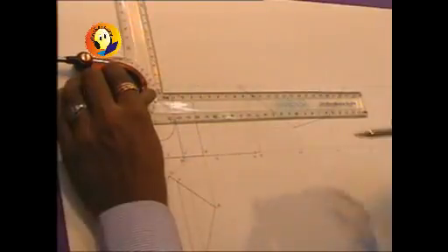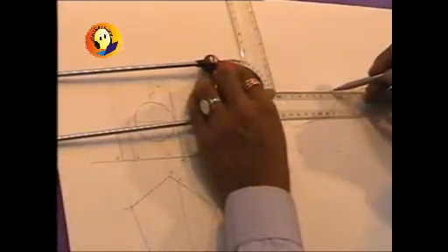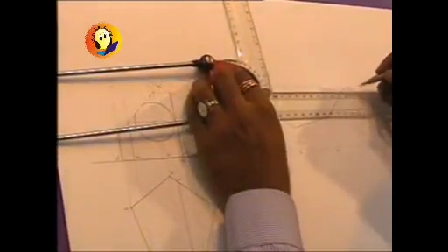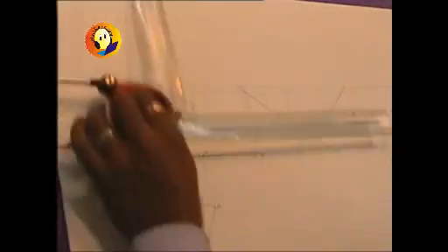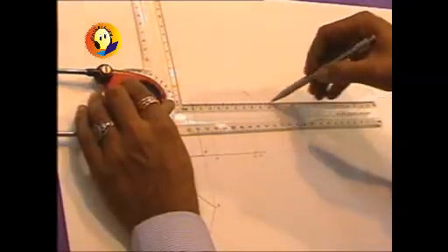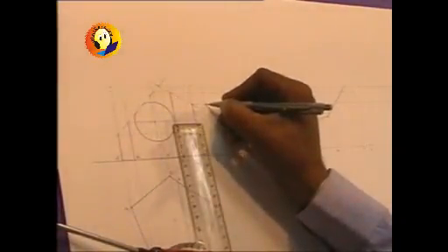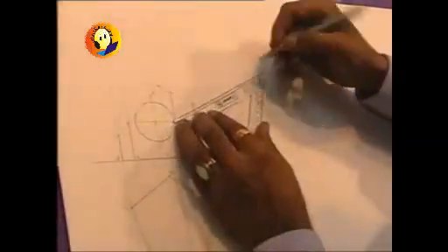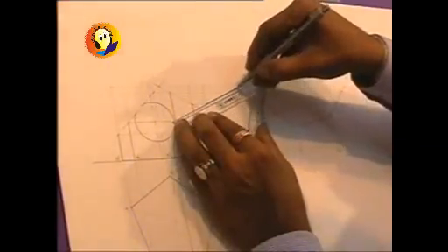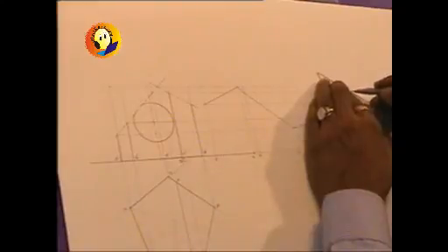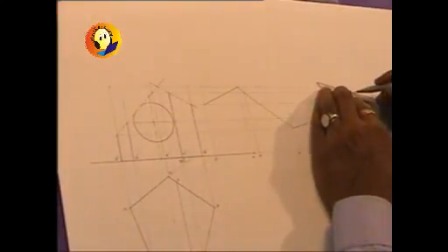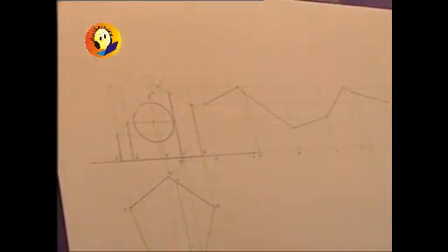And now the second cutting plane, which is cutting generator CV, and so that point can be taken ahead, and we get the point on generator C. And then generator D is cut at one point, so even the point on generator D can be taken and marked on generator D, which is occurring twice, and again they can be connected. So you will have to connect them in sequence. And what we get over here is the development once the prism is cut by the 2 section planes.